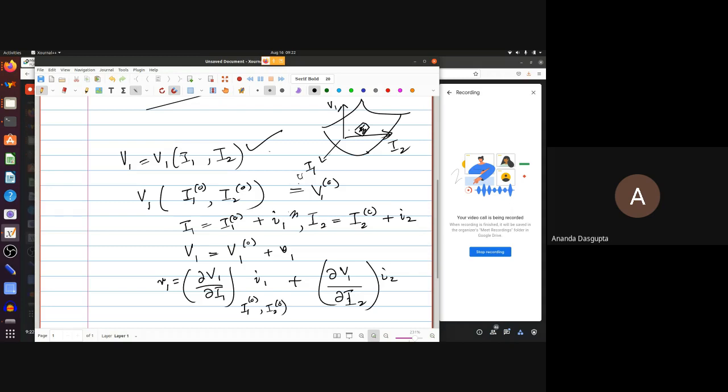Now there the quiescent point is essential because you have inherently non-linear behavior in your circuit, and you want to ensure that you are in a roughly linear region, a region where, at least, fluctuations in current are proportional to fluctuations in voltage. Okay. That is why you need a quiescent point value, and that is why you need fluctuations around that.